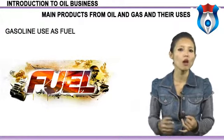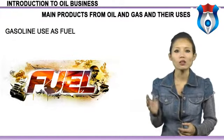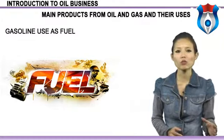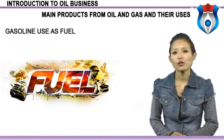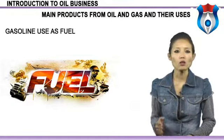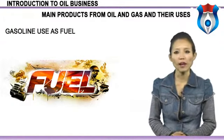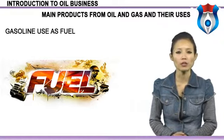Gasoline to use as fuel. Untreated gasoline shows in combustion engines a phenomenon called knocking, actually a second delayed explosion. To express this tendency to knock for various gasoline molecules, the first pure hydrocarbon with the greatest resistance to knocking, 2,2,4-trimethylpentane or isooctane, was given a rating of 100, and normal heptane, which causes a considerable knock, was given a 0. Adding an anti-knock chemical, tetraethyl lead, considerably reduced the knocking, but this is now phased out for environmental reasons.